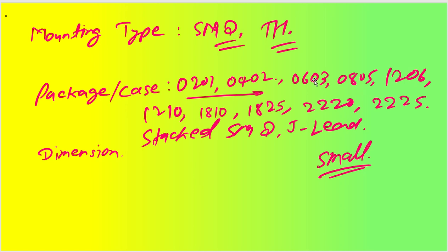But for 0.1 microfarad capacitor, you definitely go ahead with 0402 if your mounting is not that complex, just 0.1 microfarad. Okay, and the dimension of each one of them, let me just take you directly to there. Before that, what we'll do is